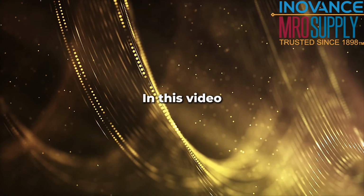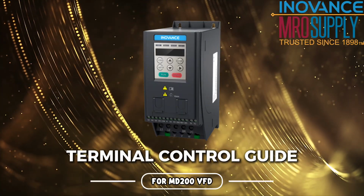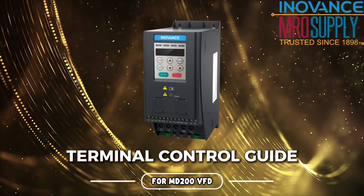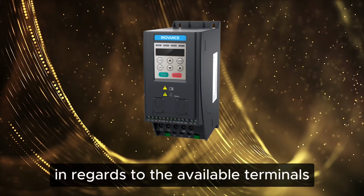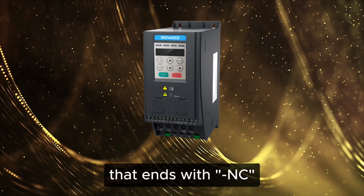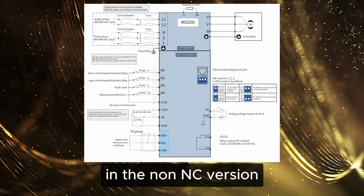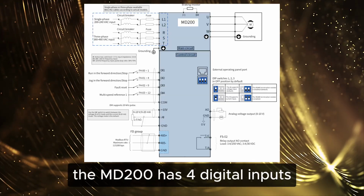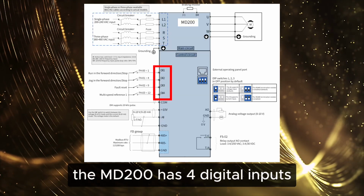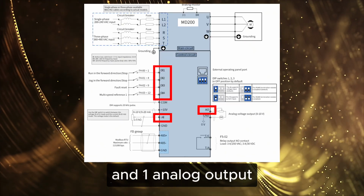In this video, we will be covering how to control the MD200 inverter drive via the onboard terminal block. In regards to the available terminals, there are two different models, one of which has a part number that ends with -NC and one without. In the non-NC version, the MD200 has 4 digital inputs, 1 analog input, and 1 analog output.